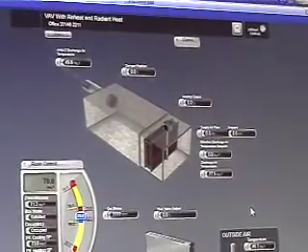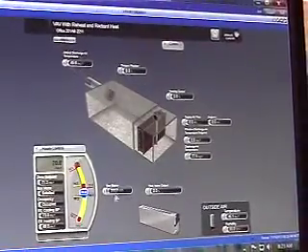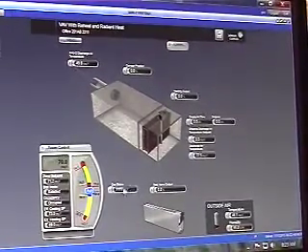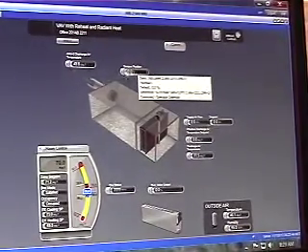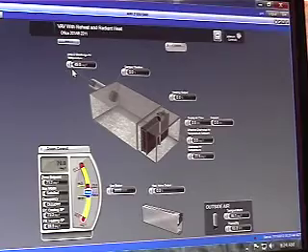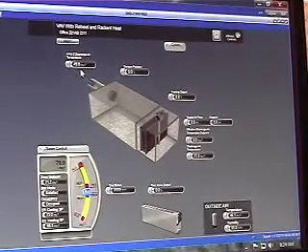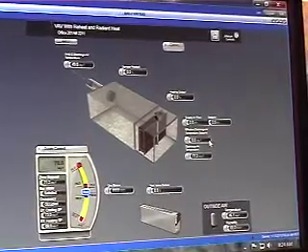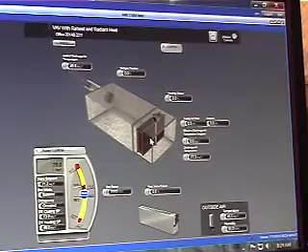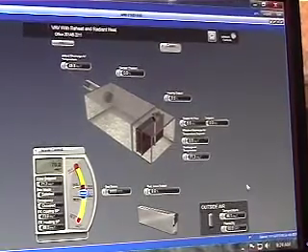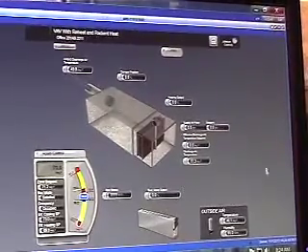You can see this is an office, looks like it's unoccupied, or has a minimum ventilation of 0. Occupancy status, not populating yet. So the damper position is actually closed with it. You can look at the discharge air temperature from the air handler. So we separated these into air handler 1 and air handler 2, so you can see what's coming into it and what's leaving, which helps to troubleshoot as far as, if you had actually hot water flowing through the coil or whatnot. This one has a radiant valve as well, tied to the radiant heater.